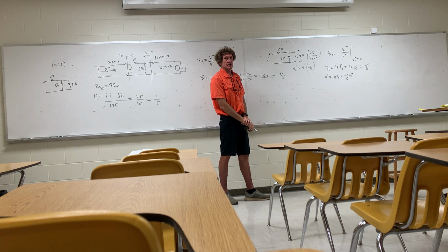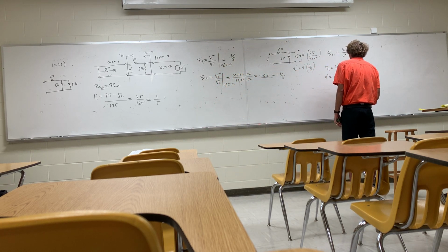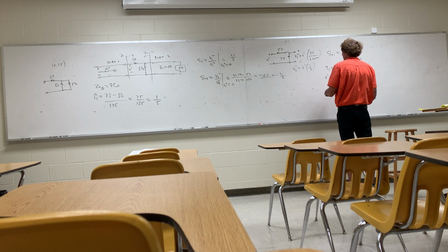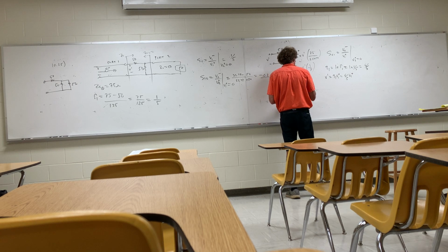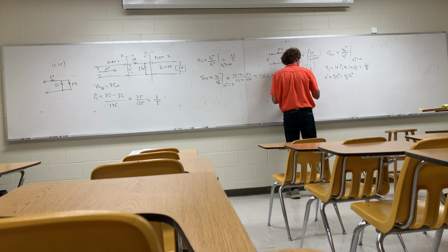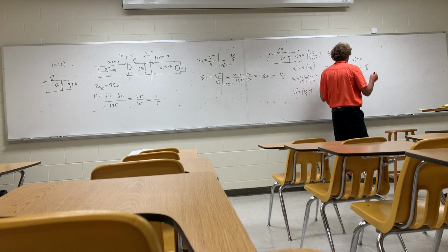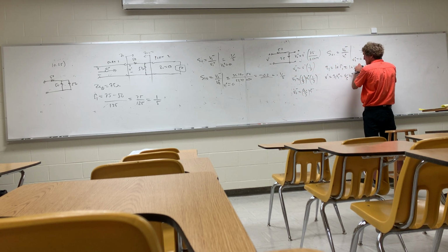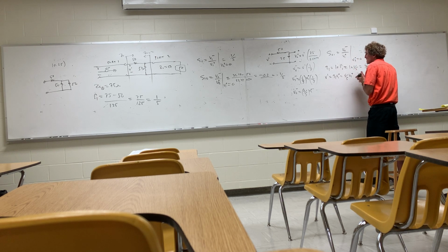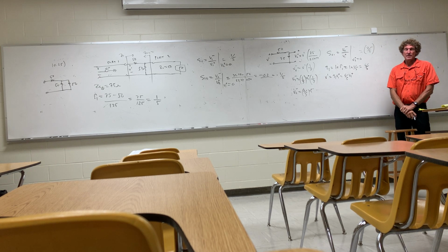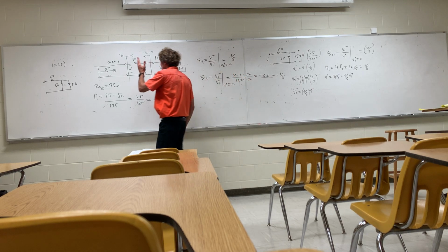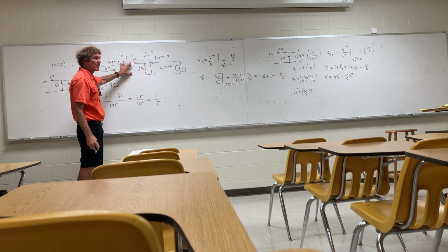I'm going to stop and let you just grasp it, think about it. Everybody agree? You good with me? All right. So what's that going to be? Well, when I take a look at this, I can say V2 minus is going to be V prime, 4/5 times V1 plus times 1/3, or really 4/15 times V1 plus is equal to V2 minus. Therefore, when I take V2 minus over V1 plus, it's simply 4/15. Does everybody agree with that? And again, the key to this thing is getting that voltage just on the other side of port 1's connection.